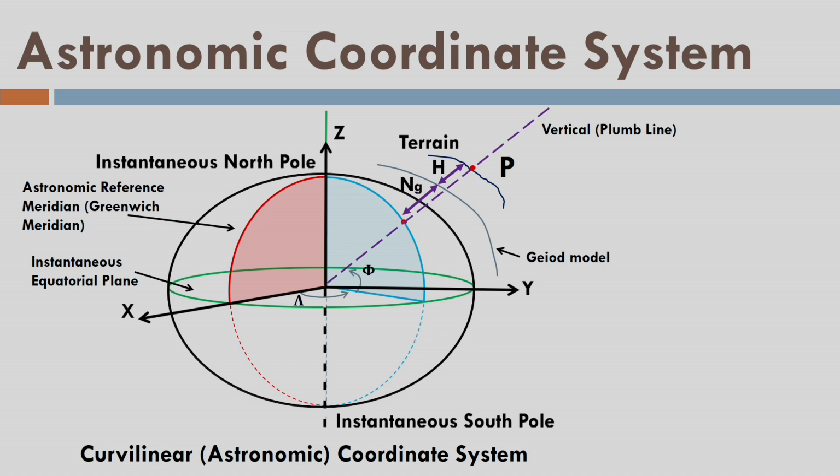They decided that for that particular region they were going to fit that particular ellipsoid, and for that they used to observe triangulation networks. They used to determine some two-dimensional points. They used to determine the vertical heights, and these vertical heights are the orthometric heights, capital H. Using this one-dimensional survey for vertical and two-dimensional survey by triangulation for planimetric survey, they used to combine this data and fit the ellipsoid through those 3D points, and that was the idea.